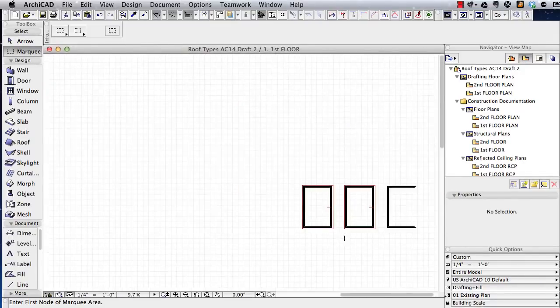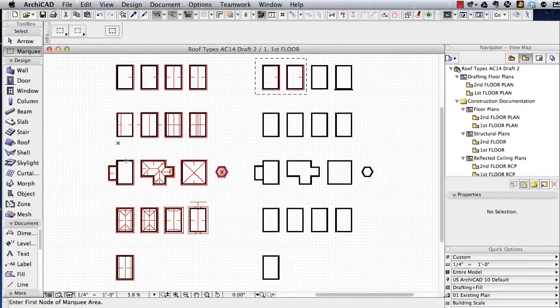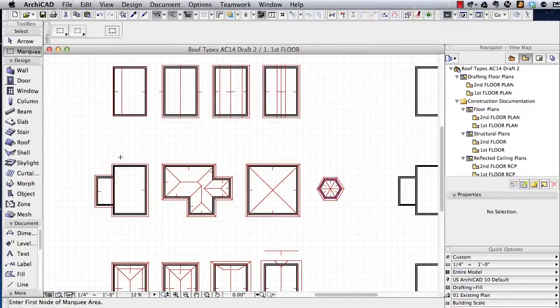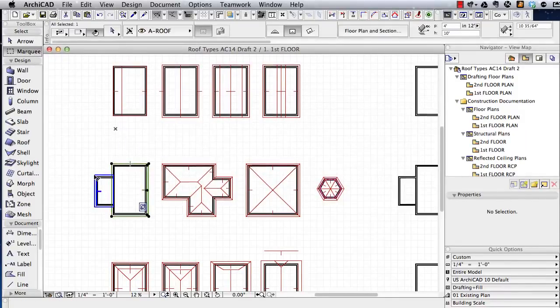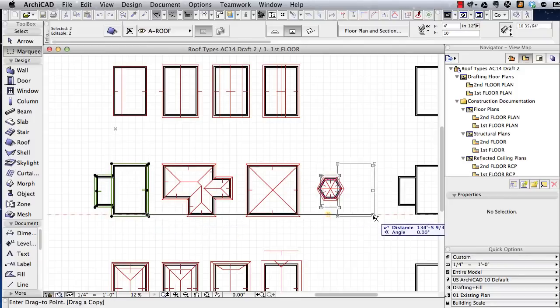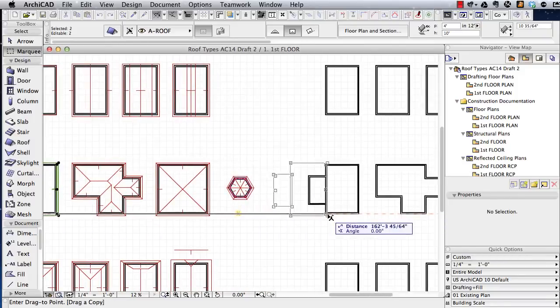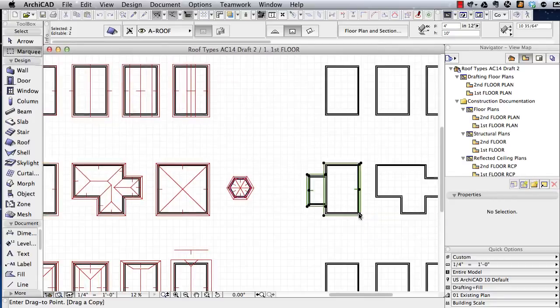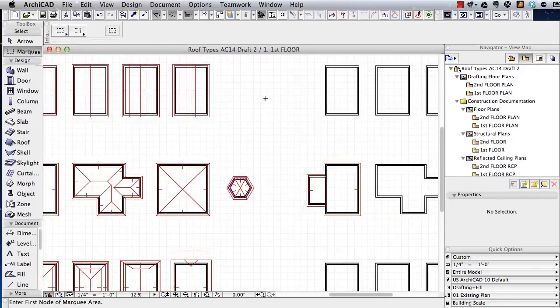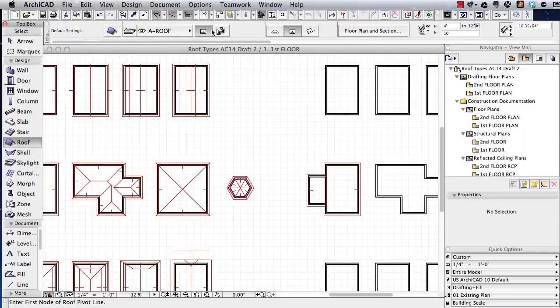Now in addition, if we zoom out here, we've got the roof that's called a skillion and lean-to roof, that is this combination here of this one shed roof and this other shed roof that's on a second part of the building. I'm just going to drag a copy of this over, because this is exactly the same way we would work in ArchiCAD 15 or 16, basically just with the single plane roof option here and perhaps rectangular pieces of roof.